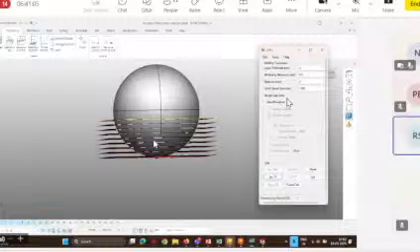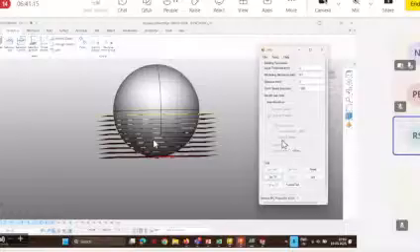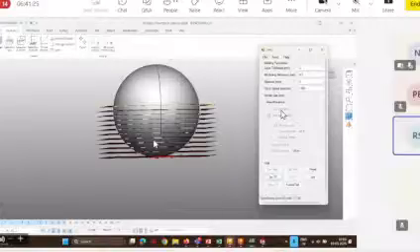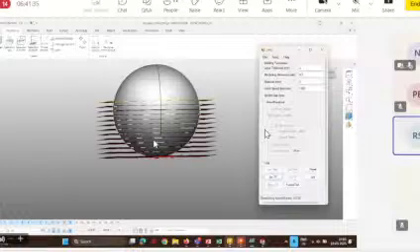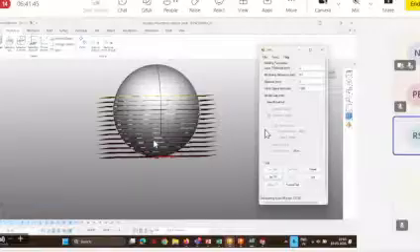And you can even see define toolpaths here. Like you can select this Hilbert curve. Then there's an option called fixed angle: suppose someone wants to print the entire part at a single angle only, you can fix that over here. You also have some contour pedal toolpaths. Not only this, you can even try your own toolpaths. Those coordinates you can import. You can create one tab over here where you can copy and paste all the coordinates of your trajectory. Then the software will automatically convert that trajectory into G code and M code, which finally you can take on a USB stick and put in the machine, and the printing can be done.